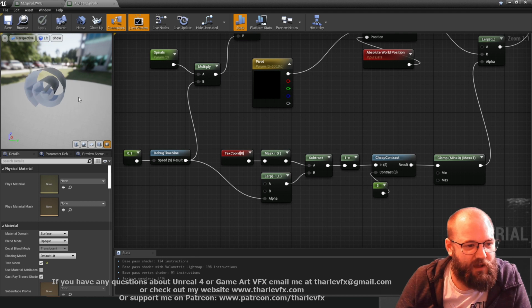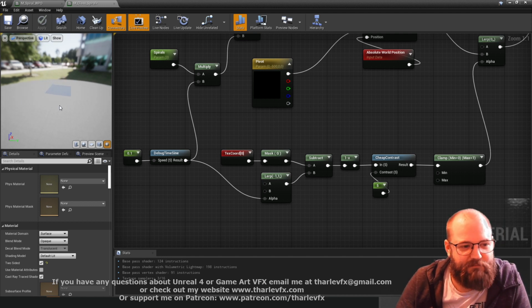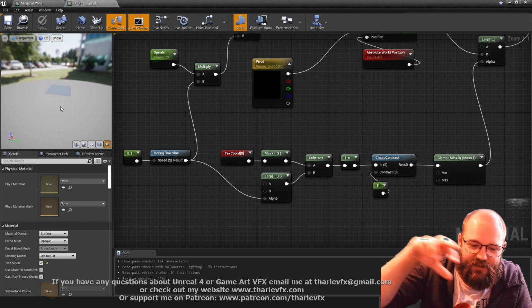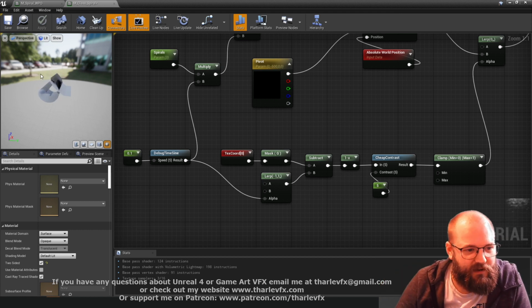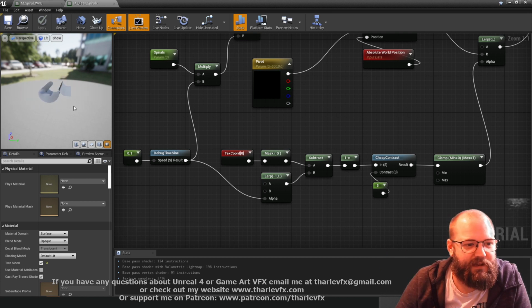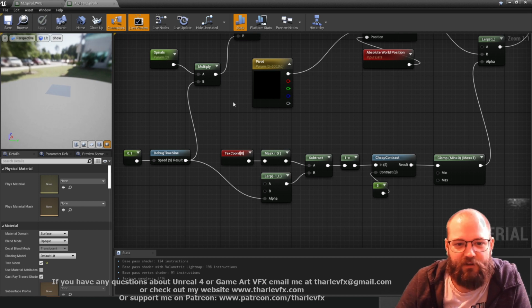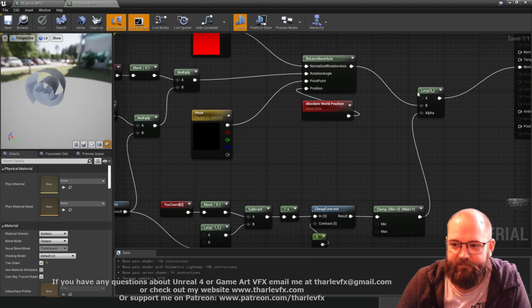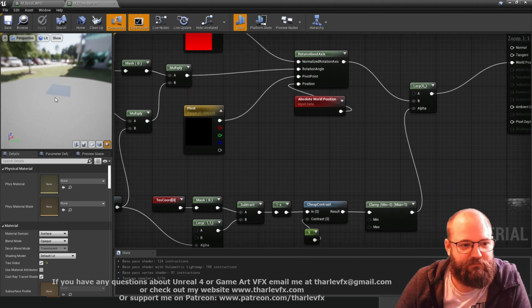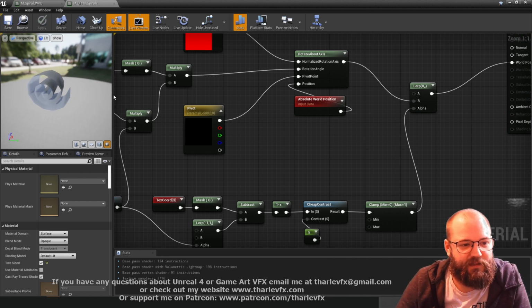Now, one thing you might notice, the spiraling effect that we're making is making the plane longer, that rotation effect. So we also want to artificially make the other plane, the flat plane, longer as well, to make it look together like they're the same sort of conservation of volume or conservation of shape. And so in our flat condition, this one here, I'm actually going to move the verts. So the bottom line, I actually want to move along the y-axis to be that little bit longer.